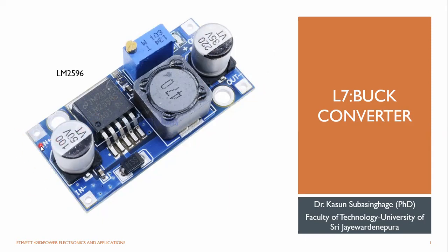So this is the control IC of the power supply, which has all the control circuits, and this is the inductor. You need an inductor for these switch mode power supplies, and you need some additional filter capacitors, the output capacitor and input capacitor, and this power diode. And there are some small feedback resistors and capacitors. Sometimes you can buy this control as an adjustable version, which means that by changing this voltage, you can change the output voltage to any desired level.